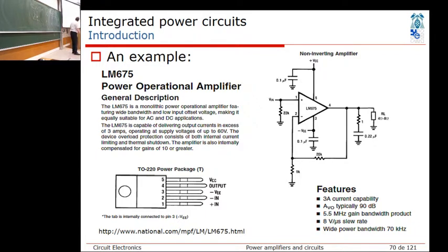And then we also have this, at least for my eyes, funny thing: there's a 1 ohm resistor with a capacitance in series, meaning that for high frequency currents it gives a lower impedance route to ground.